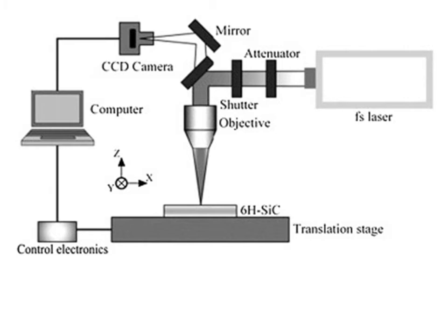Then we are using a shutter here. The reason this shutter is used is that during this procedure, we will have to turn off the laser beam or turn on the laser beam, depending on whether we want to do the welding or whether we want to move the laser head to a different location, so that on the way in which it is moved, it should not fall on any object. So sometimes you will have to turn on the laser, sometimes you will have to keep it off. But normally we'll be using very huge lasers, which require a lot of procedure for turning them on, and it is not advisable to turn off the laser during this procedure.